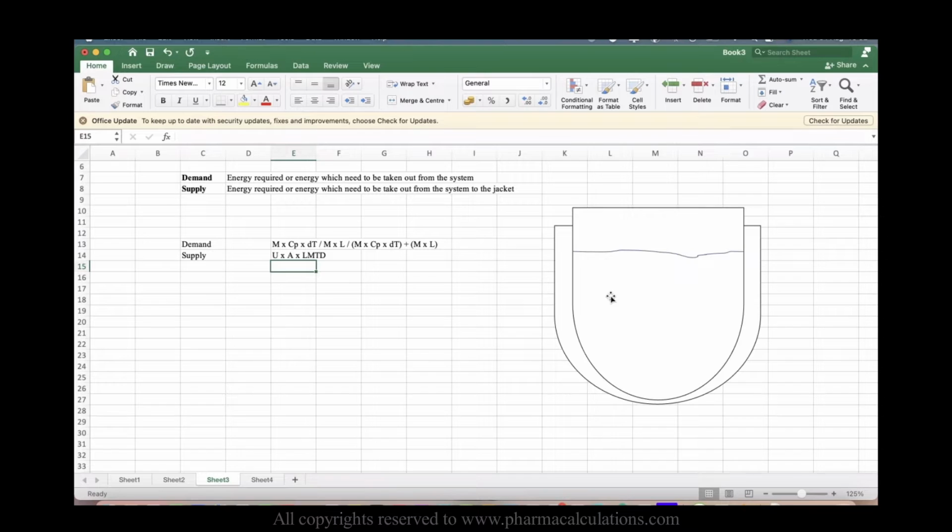and at the condenser end we are going to take out the same amount of heat which is being given from the reactor. So ideally, if you are able to provide the same amount of heat transfer area at the condenser like what the reactor is having at a specific point of time, it is adequate. In other words, the amount of heat transfer area which is available to the reactor shall be provided at the condenser end also.